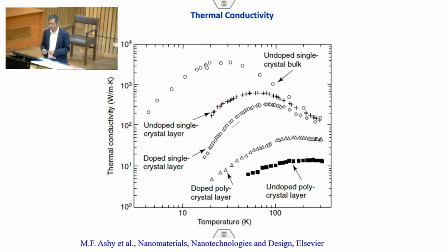Am I clear? So overall, the idea is to take different approaches to control the phonon transport in various regions of the phonon spectrum. So high frequency phonons can be blocked by alloy scattering because their wavelengths are of the order of a few atomic spacings. Okay, so phonons can have different wavelengths, and therefore their scattering will depend upon the relative grain size of the materials. So now comes the nanoporous material.